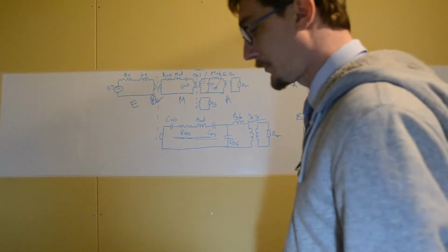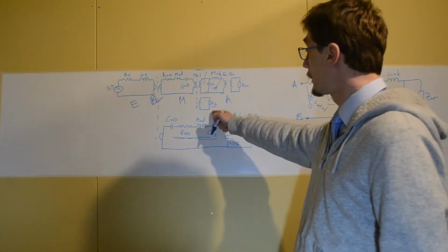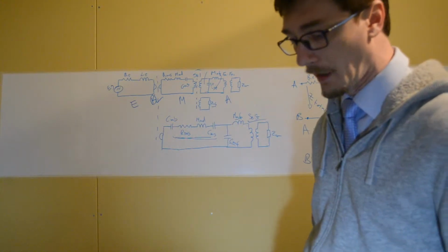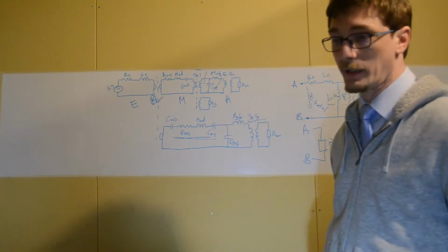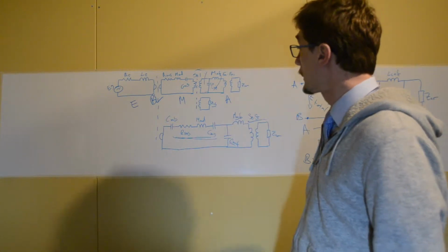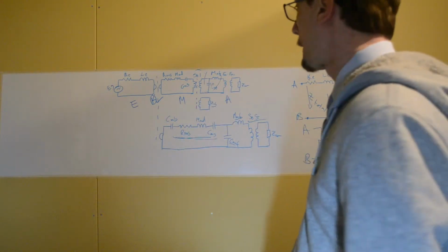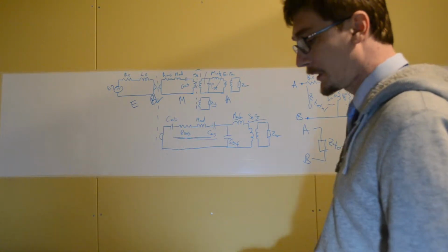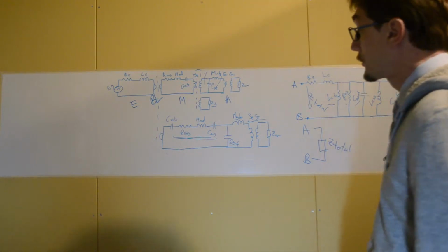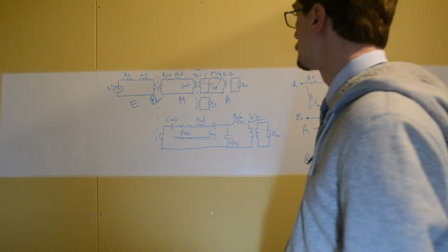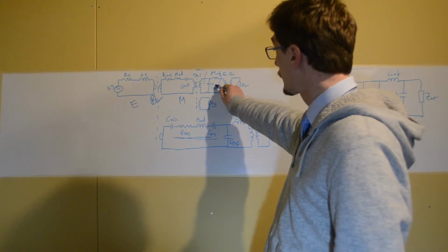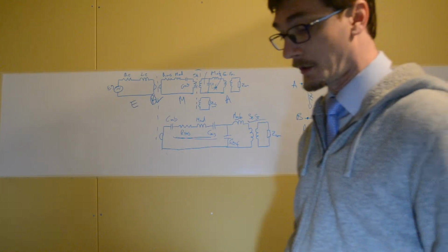So the back of the diaphragm vibrates into an enclosed volume of air here. This is the back one, and I've marked it as an unknown impedance, ZAB, right? So that's impedance acoustic back. The front of the diaphragm is a little bit different. It vibrates into this small space between the diaphragm and the phase plug. So we have a bit of a compliance there, which is marked as CAF, compliance acoustic front.